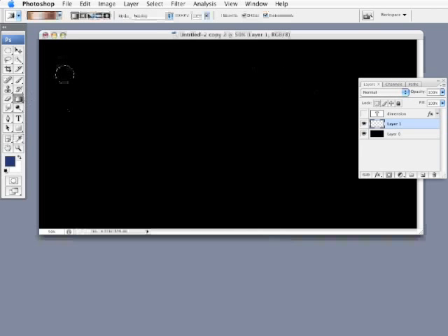And inside that selection, I'm going to hold down my Shift key and draw from the top of that circle to the very bottom of it, just like that. So there it is, filled in that selection. And like I said, I don't need the color, so I'm going to go ahead and press Shift Command U or Shift Control U. That will remove the color information.